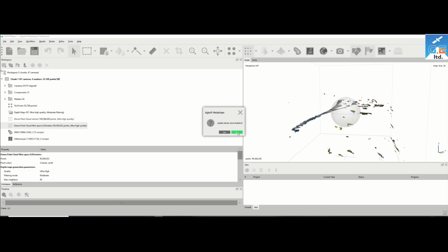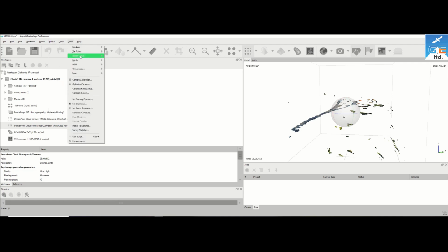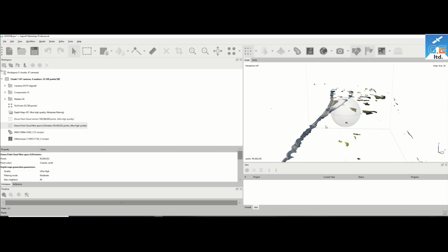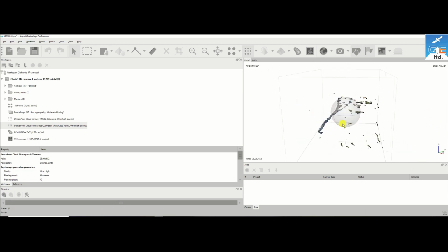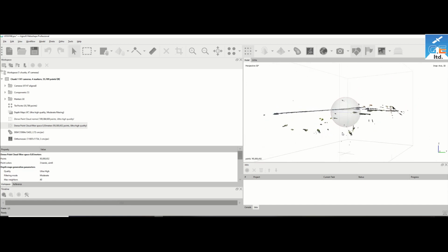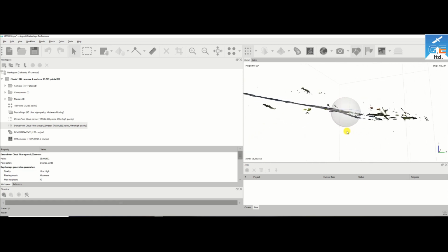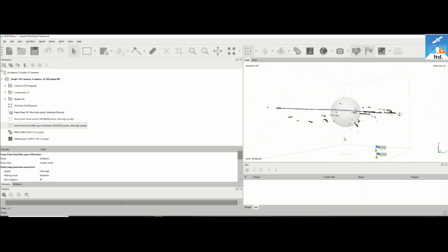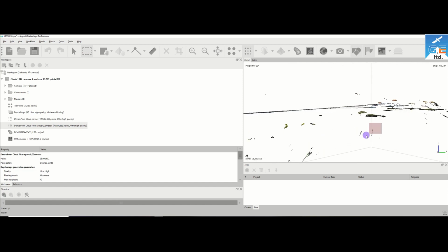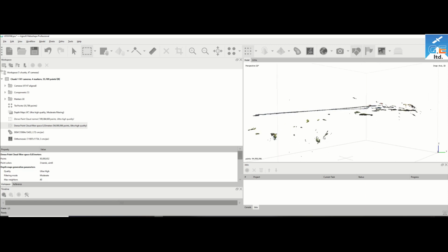If you don't update the dense cloud, the filter is only a temporary filter. So we can remove the filter, and it is only a visualization of the selected filtered point cloud. Clear, it is not perfect because there are some points that do not represent the real surface, and so we need, for example, a selection like this of the points that are noisy, and cancel them.